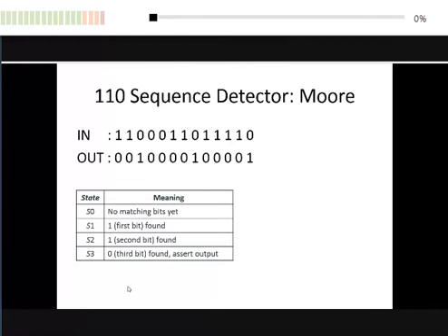The sequence can be anything. In the exam, of course, we try to limit the sequence to 3 or 4 bits only. It depends, but it is always like this. This one is quite easy. There are more complex sequences. For example, if the sequence you want to detect is 010 or 101, then you will get more headache. That one we discuss later on. But this is what we mean by sequence detector.